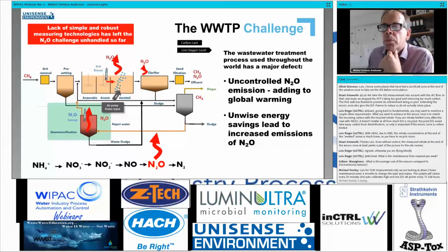One of the backsides of energy optimization is often that when you start to squeeze and optimize the aeration, lower the oxygen set points to save energy, but also increasing loading as cities grow bigger, then nitrous oxide becomes more of a problem. And without a visualization of the problem in terms of a measurement and a graph, then it's really hard to do something about the problem.